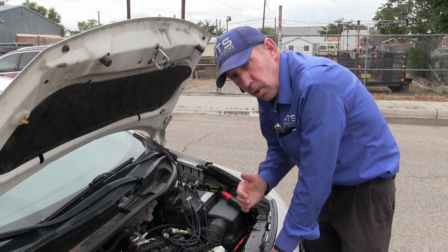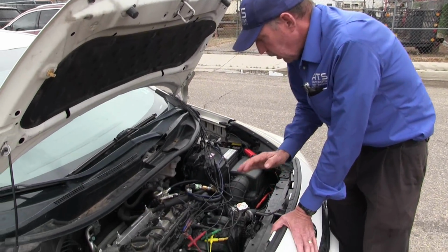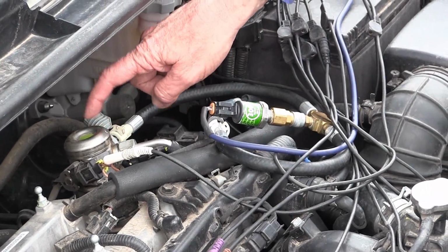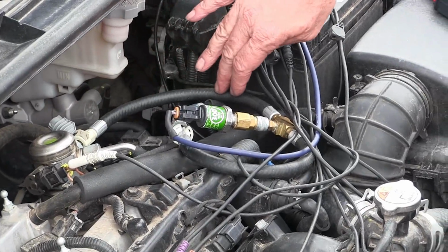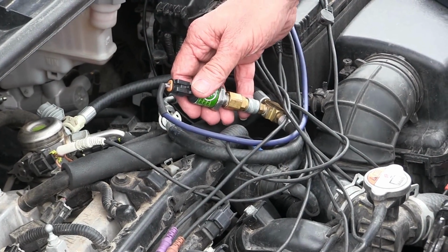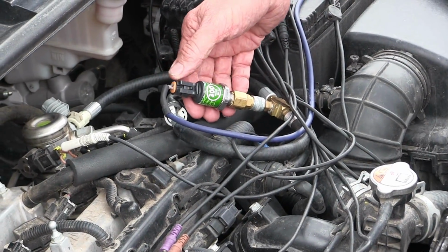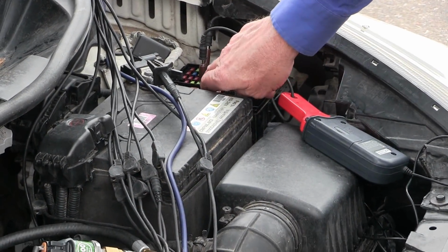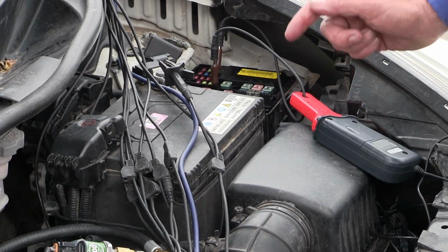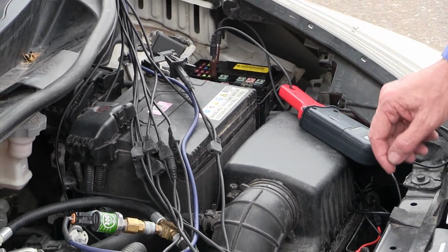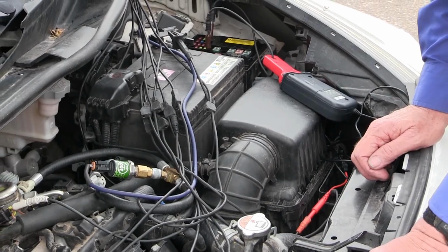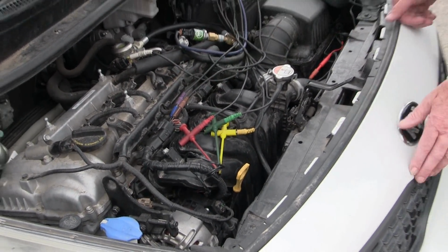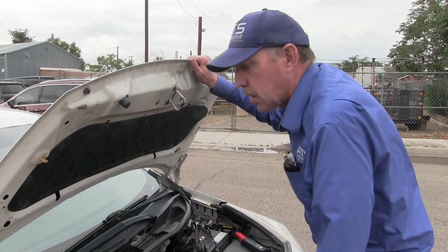In order to check whether the fuel pressure is falling away, I want to make sure we catch it. So I took the fuel line off of the high pressure pump, the feed in, this is from the lift pump, and I've teed in a pressure transducer, and this is on blue, channel 4. Then I pulled the fuse for the fuel pump, that's the lift pump, and I've got an amp clamp on that, and that's orange, channel 7. Then I've got injectors on brown and purple. So now let's go ahead and take this for a drive and see what's going on with this vehicle.